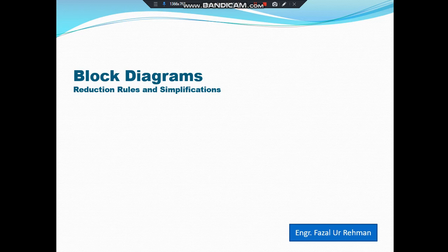Actually, so far we worked with individual subsystems represented by a block with an input and an output. When there are more complicated systems, they are represented by interconnection of subsystems. We want to represent multiple subsystems as a single transfer function. In this chapter, multiple subsystems are represented in two ways. One is the block diagram technique, and another is the signal flow graph.